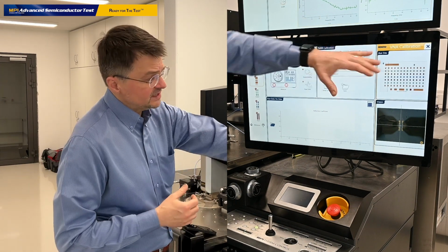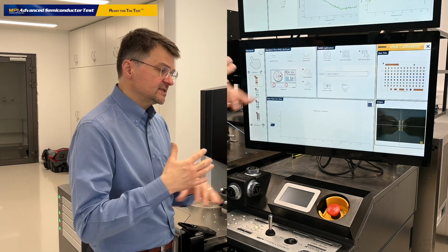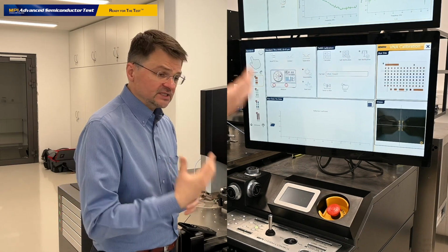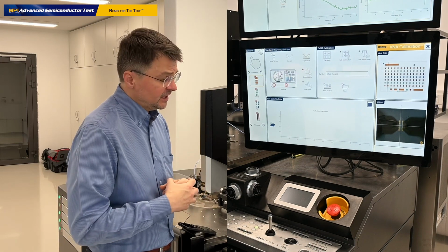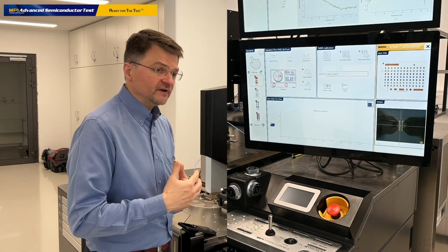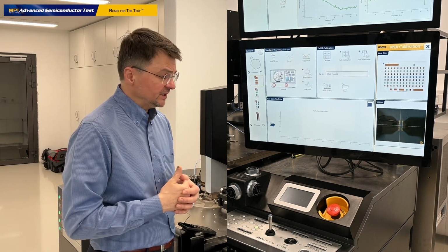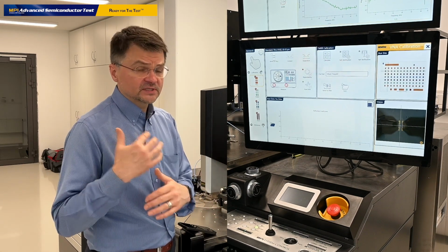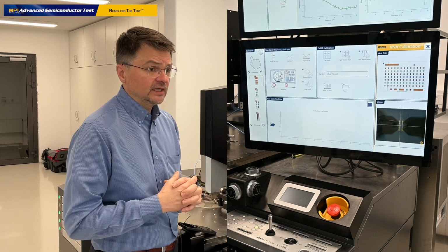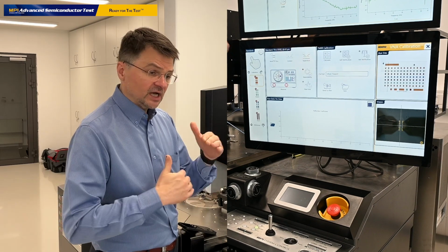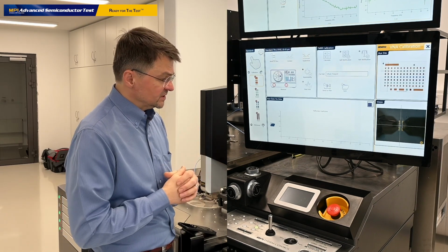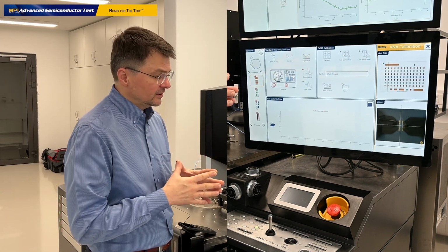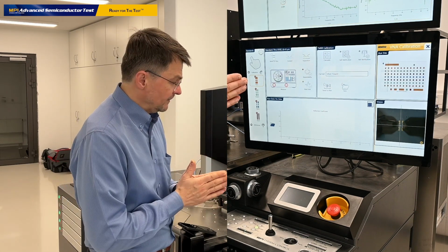And last but not least, we have other settings for so-called golden verification. This is the possibility that Calibria gives to any operator to measure well-known devices after the calibration process is complete and compare measured results with predefined parameters from the database and make sure that possible calibration errors are within the margins which are initially defined. And we will have a little bit more detailed look into that feature as well.